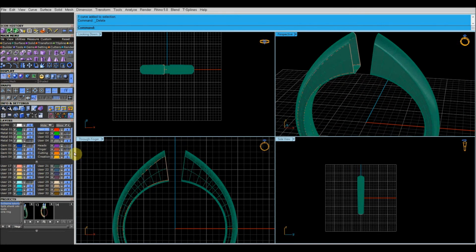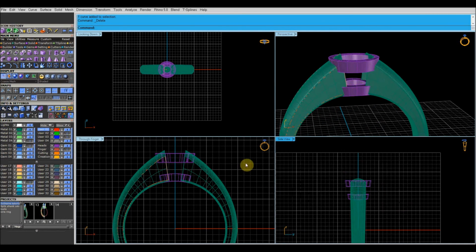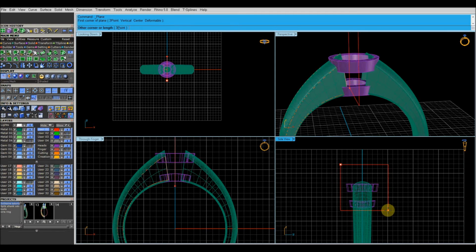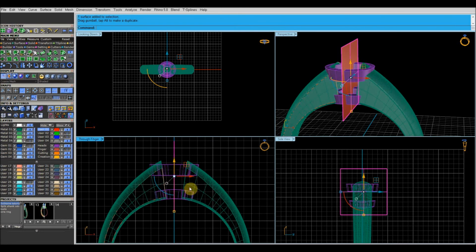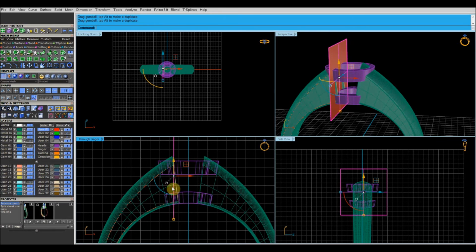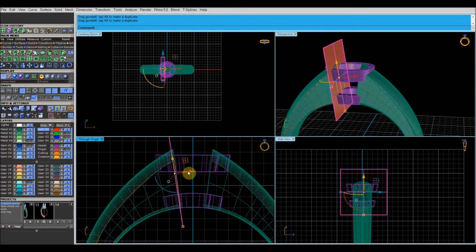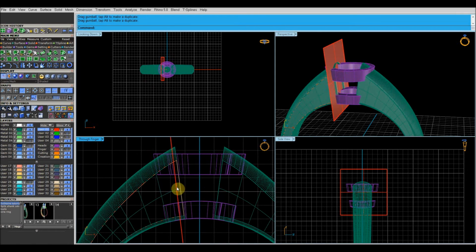Couple of easy ways to deal with this. Let's just bring this back just so I don't go too far. I'm just going to put a surface up here. So go to surface, and down here to plane from corners. Put up a little surface. Move them. And I'm just going to chop off a chunk here, just in far enough that it gets everything.